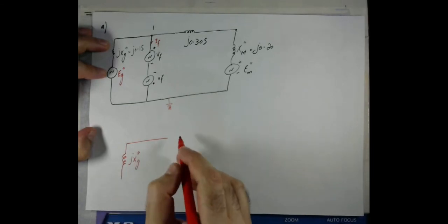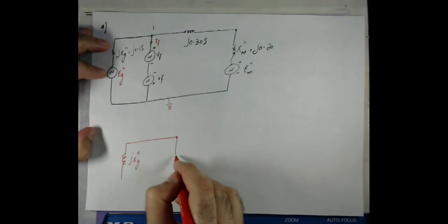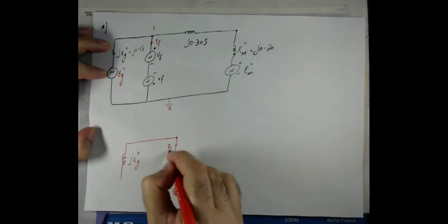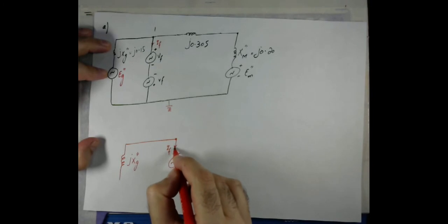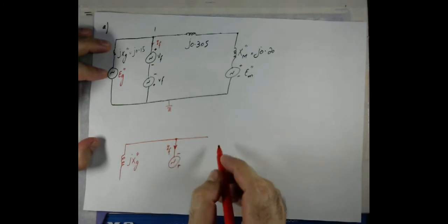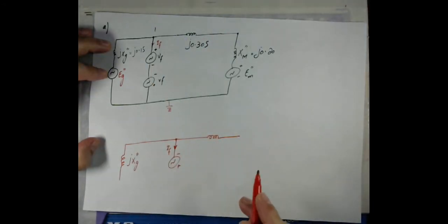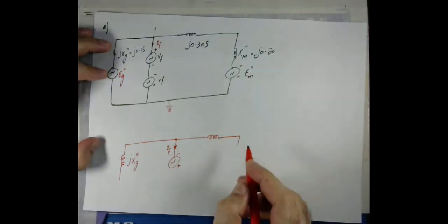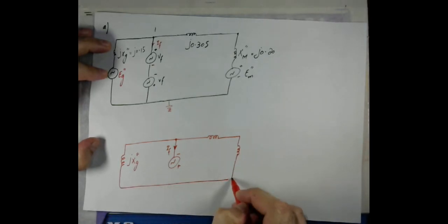Then we have bus number 1. We will only consider this source which supports the direction of the current. Here we have the fault current with this direction going downward, and that is the direction of the current, and then we have this particular reactance and that of the motor as well. So that will be the Thevenin equivalent.